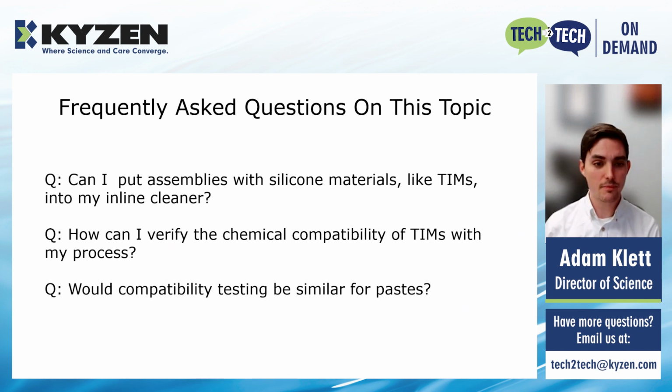And then the last question I have here is, would compatibility testing be similar for pastes? As you saw in this particular case study, we tested pads, but as I mentioned, these thermal interface materials come in a variety of forms and methods, and a lot of people use dispensable pastes, and the answer to the question is yes. The simple answer is yes. There might be a slight difference in the logistics on how to transfer the materials between vials and things like that to make sure that you don't artificially lose any material when you're doing your weights and balances. But in general, it's a very, very similar process. All right, so those are our frequently asked questions, and that's the end of this case study.